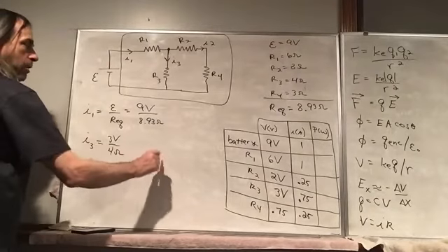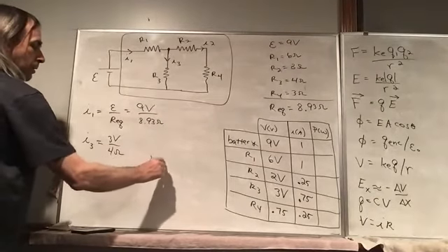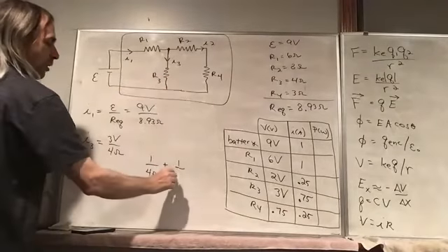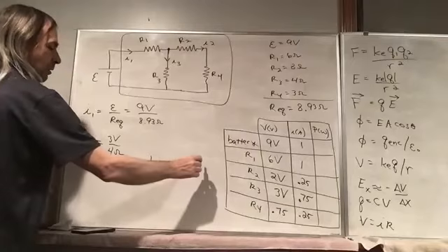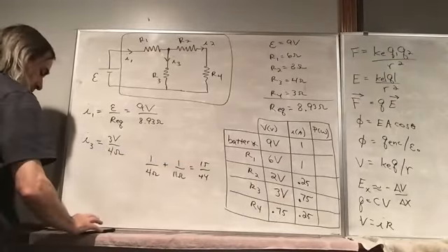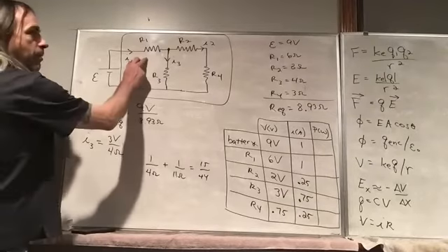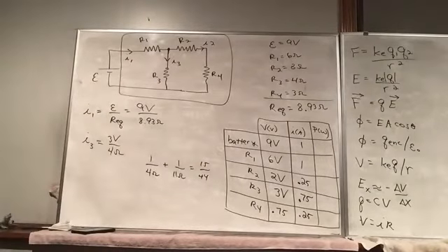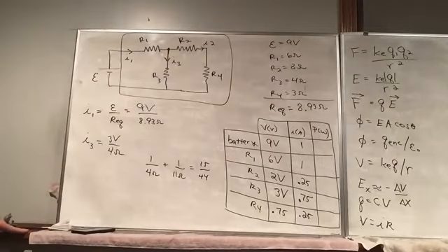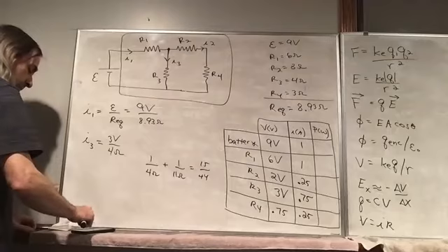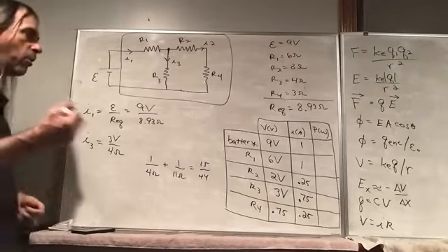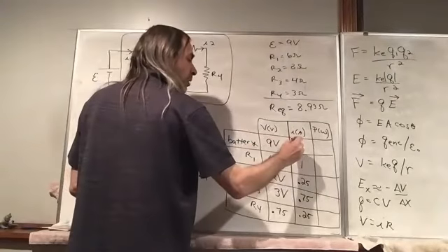So if we do 1/4 ohms plus 1/11 ohms, yeah, that would be 2.93 plus R1 is 6. So yeah, 8.93, that checks out. So I1, that would be 9 volts. I'm going to do 1.008 and just see if the numbers work out any better.